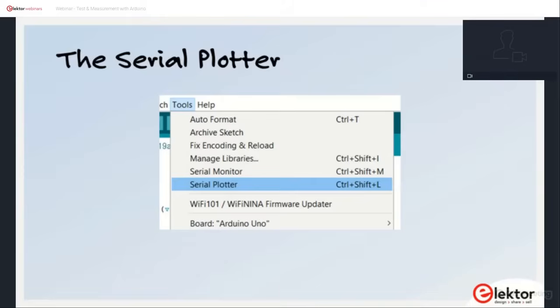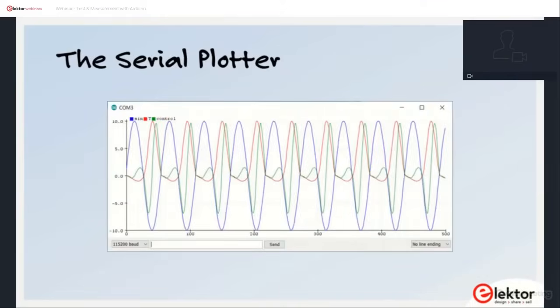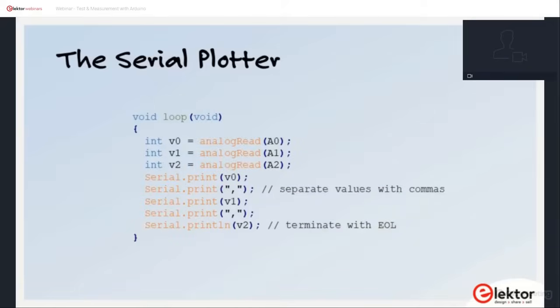By using the Arduino serial plotter built into the IDE, you can quickly make a simple oscilloscope. It is not really suitable for doing time measurements, but it allows you to visualize signals, analog as well as digital. Unlike digital inputs, it is not possible to read all the analog inputs at the same time. Therefore, signals will be out of phase unless you timestamp the samples, with the Arduino function micros for example, and correct them for time differences.